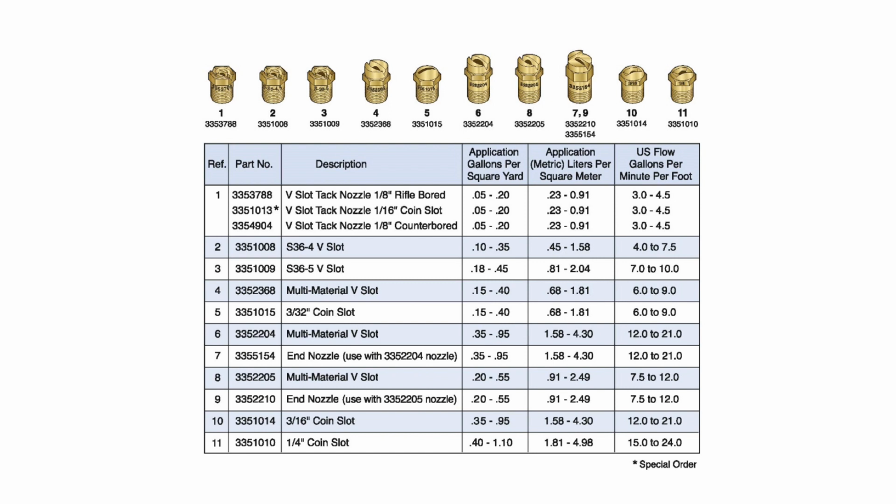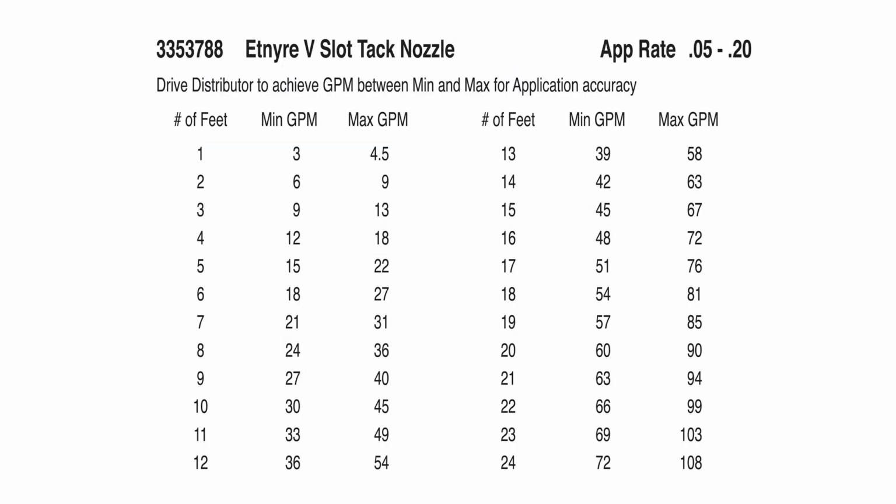Now, the nozzles are also part of what we call calibration. Don't look at what our rate is. The rate to me is a funky number. Look at the flow. And this is where the app comes in. It takes all of this into consideration. But you can figure this just with a simple thing of, if I pick this nozzle out, 7 to 10, you can multiply that by your width, and it will tell you what gallon per minute range you want to read in. We also publish a book that will show you with the nozzle we have.